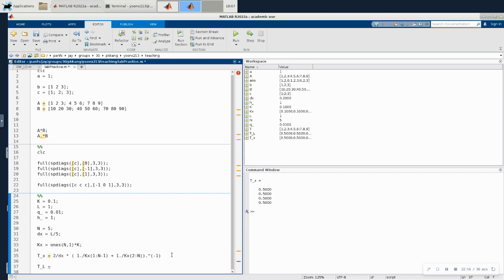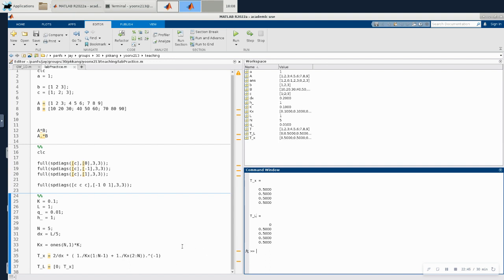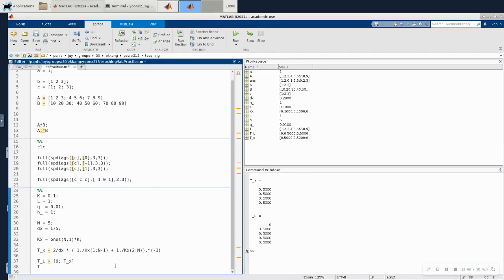And if you look at the boundary condition on the left-hand side, the inlet boundary is defined by the flux boundary. So we don't have to have the transmissibility value on the inlet interface. So we will use 0 value on that interface. So we have Tx. Okay, let's run this, and we have now the TL transmissibility, and likewise we have TR.